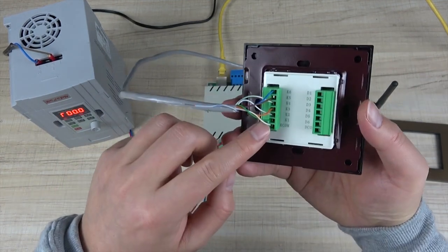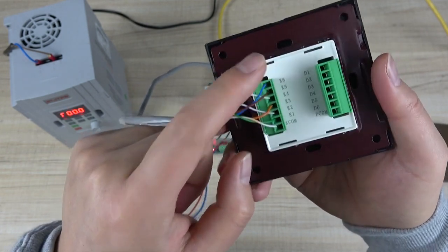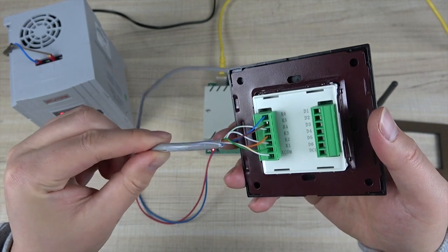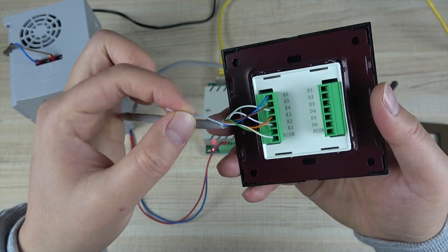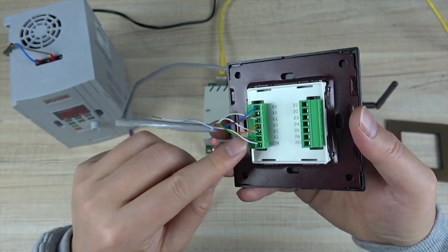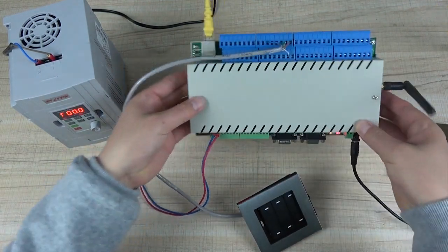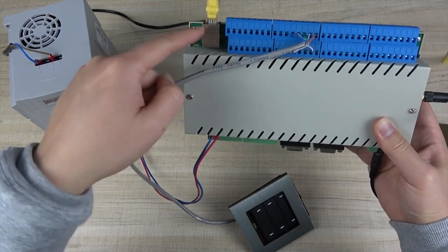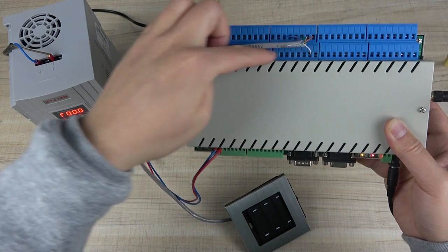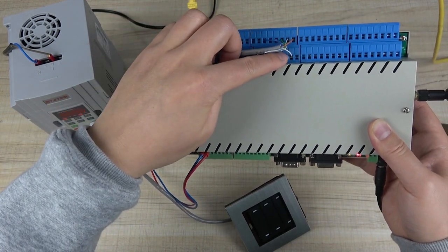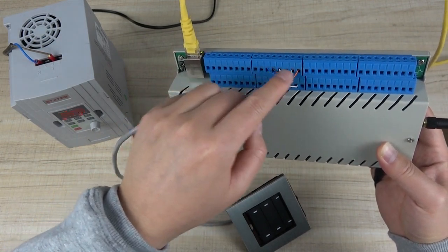So you can see this is the line for Kcom and K1 to K6. For all these lines, you can use a Cat5 network cable. So in total we use 7 lines, and the remaining 1 line is not needed. And this Kcom is connected with this one. This is for digital input, 16-channel digital input. The COM is at this row, so I use this hole for Kcom. And K1 to K6 are at this place.